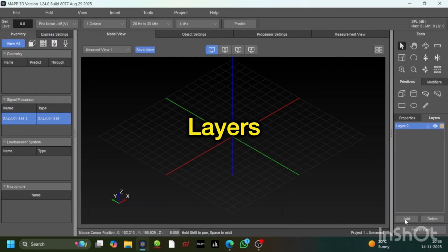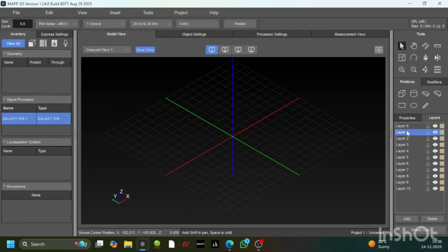So now I'll make different layers. One layer might be the plane, the surfaces that I want for the venue. The next layer can be the stage. The next layer can be the speaker tops. The next layer can be subs, front fill, and then the microphones that you'll place so that you get to see the frequency response on the ground. Okay, so these are the bare minimum things that we'll start to design here.